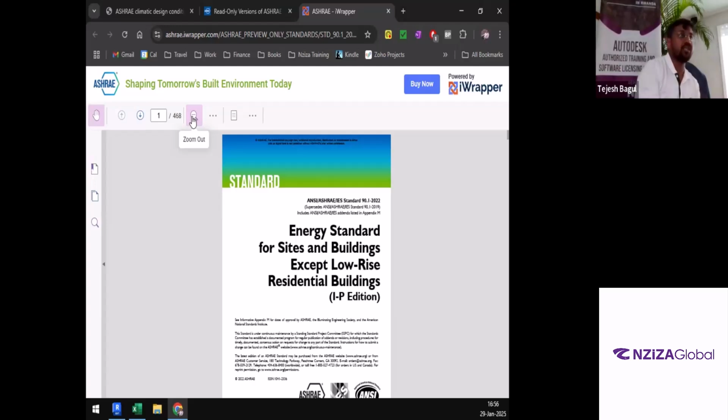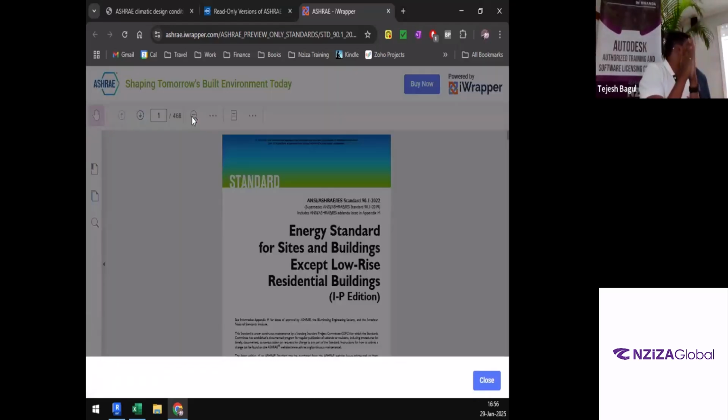So yesterday we had a good discussion regarding a single pane and a double pane window, right? Single pane window will always have low thermal resistivity as compared to double pane window. So we as engineers need to push the architects and owners to make sure that they understand that putting in a two pane window, maybe with air in between the two panes or argon gas or any other inert gas in between the two panes, will increase the thermal resistivity of your facade so that you don't have to run the AC as much.